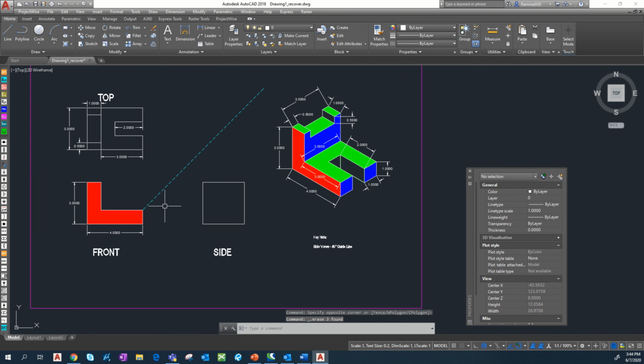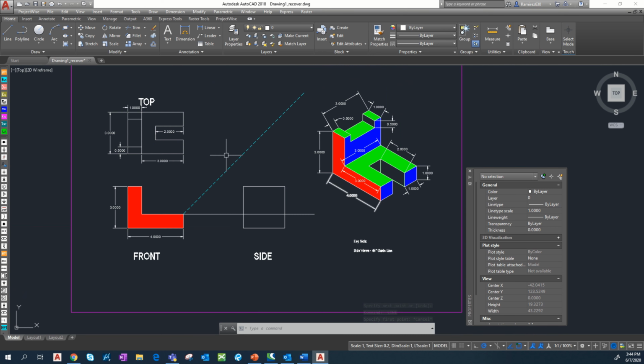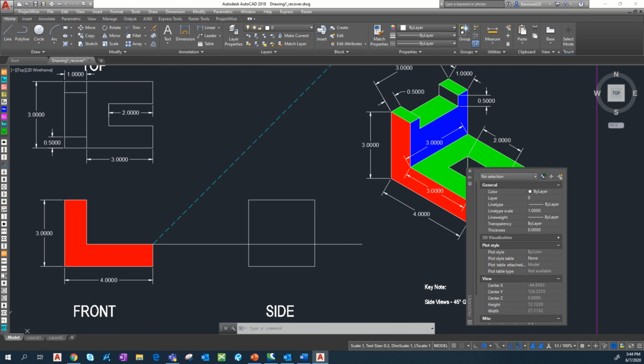So we're gonna start out with the front view. So you guys are just gonna draw straight lines over. So for this one, that's gonna be this section. And you guys could actually use the top view as well. So we're just gonna draw this straight, go down.